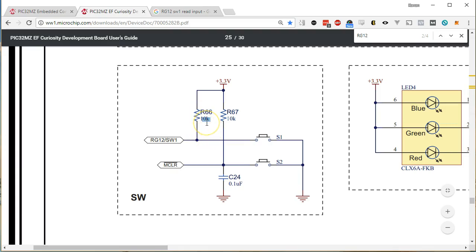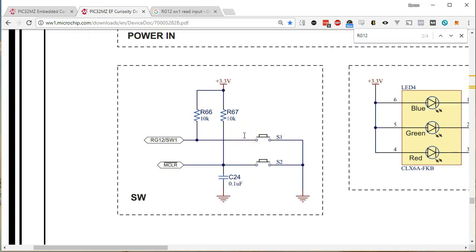If you took this resistor away and pushed the switch down, bad things would happen. You would most likely fry something because the amount of current going through here would be incredible. It would be literally as much as your computer, USB adapter, or batteries were willing or able to handle. So anyway, that is what we have.